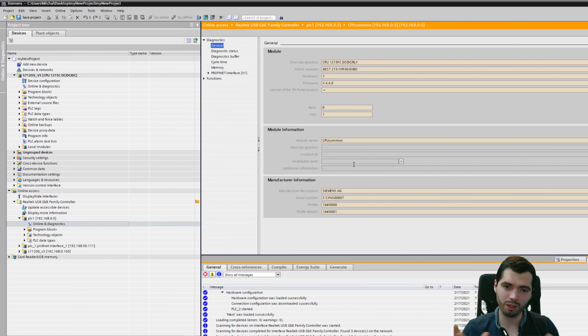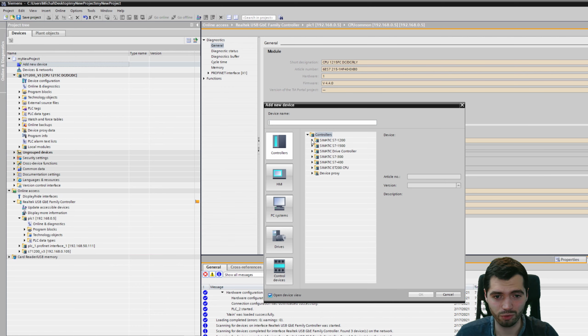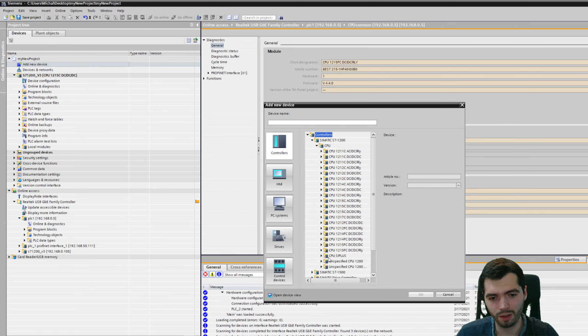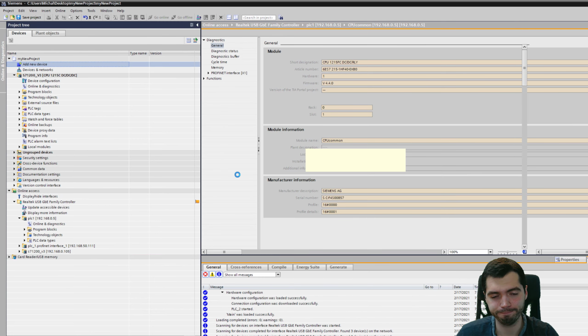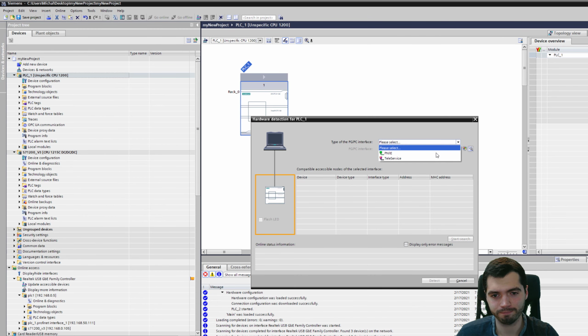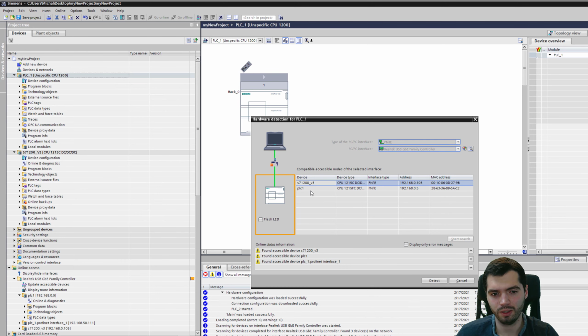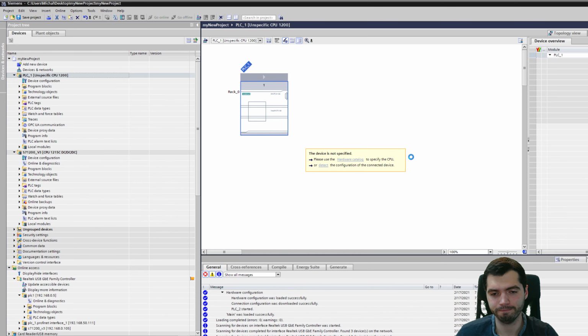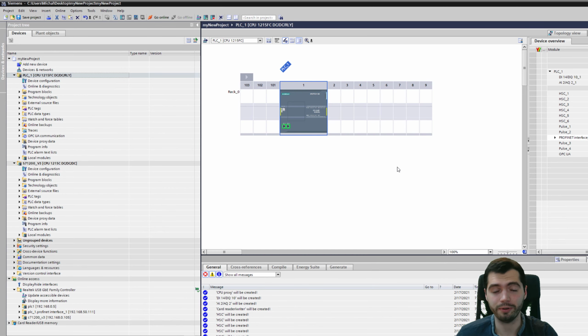So if you are seeing a similar problem where you maybe just can't detect this PLC, you can't go online with it, make sure to also give it a name. Give it a name, give it an IP, and it should be rather happy. It should tell you what it wants. And now if we go back and try to detect it, it should all work fine. So we go unspecified CPU, detect, PN/IE, USB GBE. Yeah, I have my PLC1, detect, and now it finds it fine.